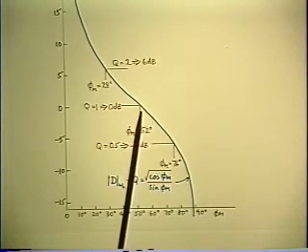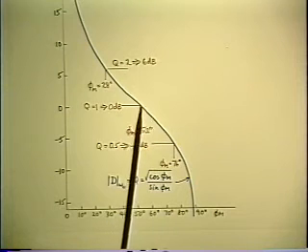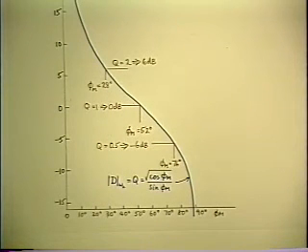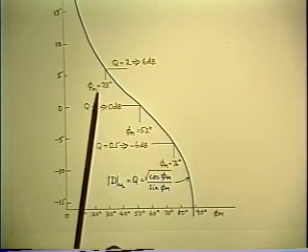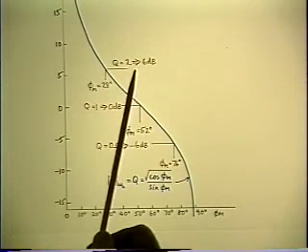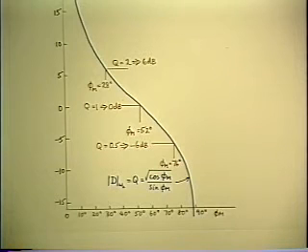If you go in the other direction, and when I asked the question at the very beginning of this section, how much phase margin do you think is necessary, I was pleased to hear no one said anything as low as 30 degrees. Because look what happens. 28 degrees gives you a Q factor of 2. 6 dB of peaking in your closed loop response.